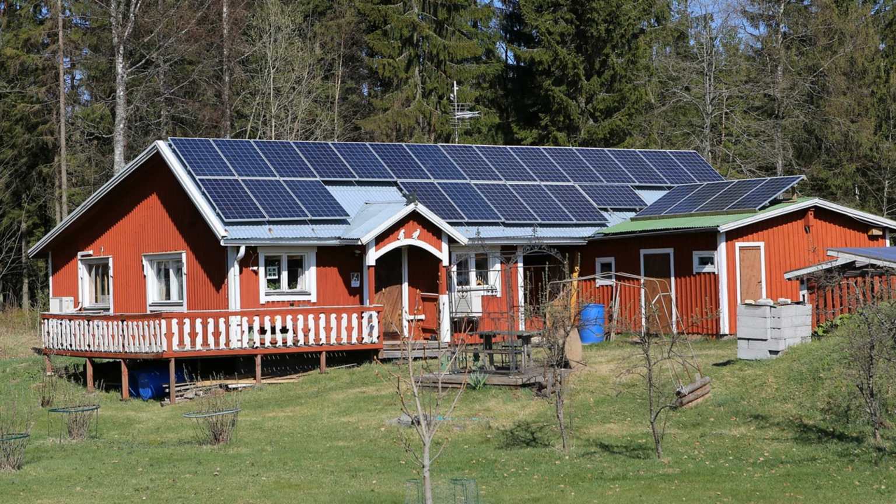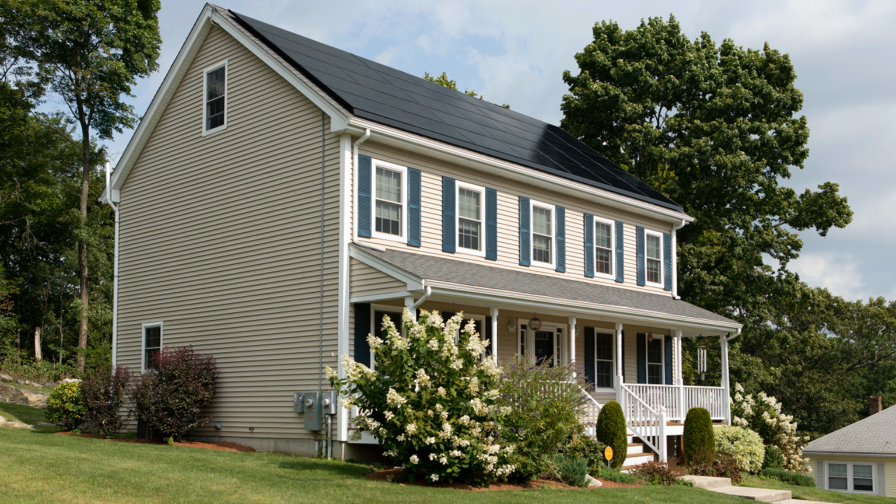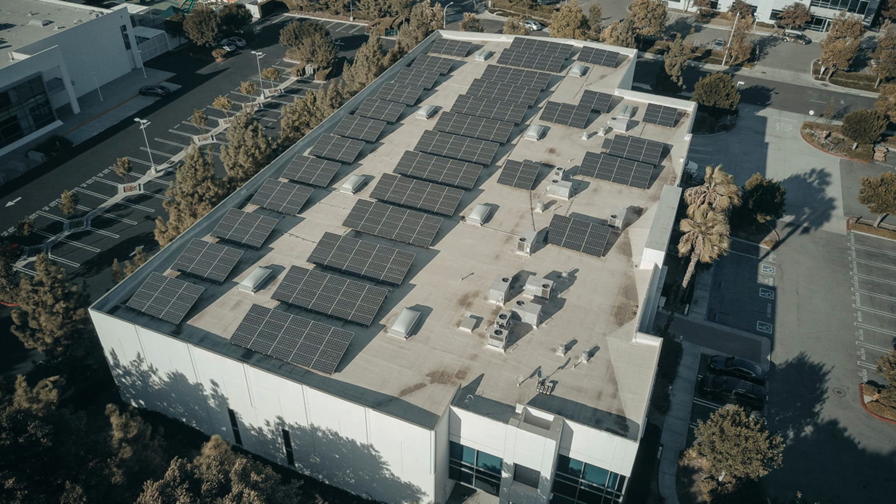You're losing power when you lose voltage. So it doesn't make sense to spend thousands of dollars to generate power just to throw it away. So for photovoltaics, I would suggest you want to keep all your total voltage drop below 2%. It'll save you thousands of dollars in the long run.